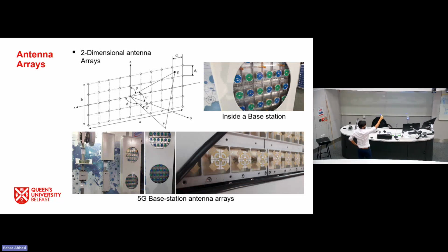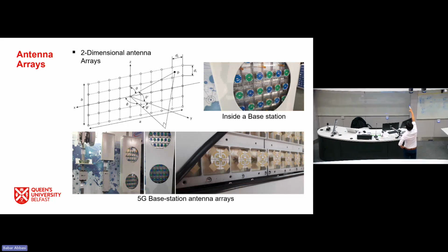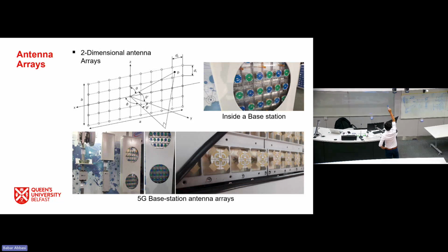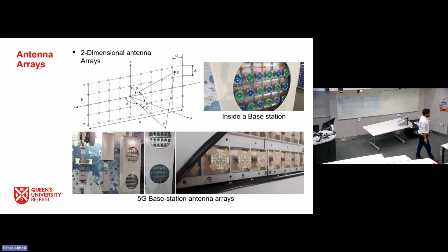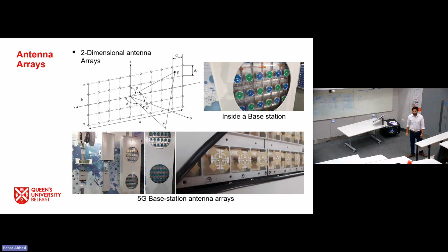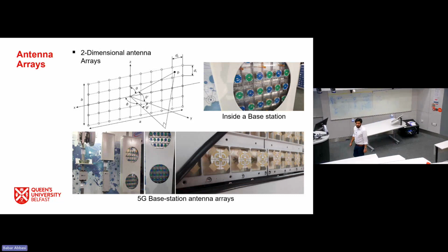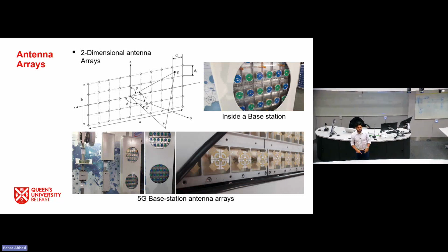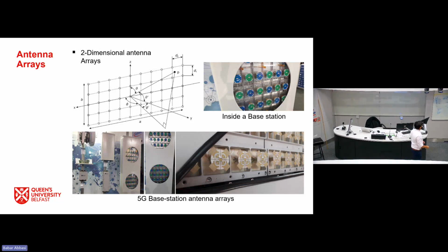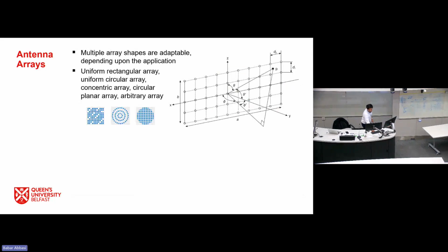And this is not a single antenna, it's an array of antennas, and the array formation is something like that. There are multiple antennas along the x-axis, multiple antennas along the y-axis. So it's called a uniform rectangular array. Why do we use the word uniform? Because the gap between these antennas is uniform. Rectangular because it has a rectangular shape. Array because there are a bunch of antenna elements. The same antenna theory applies. Everything else remains the same.